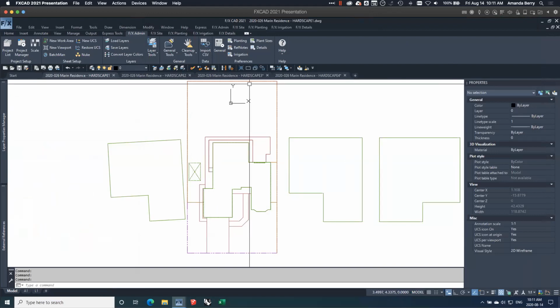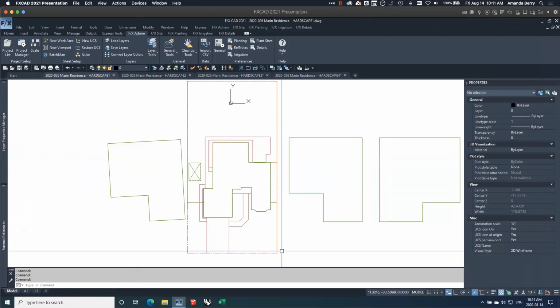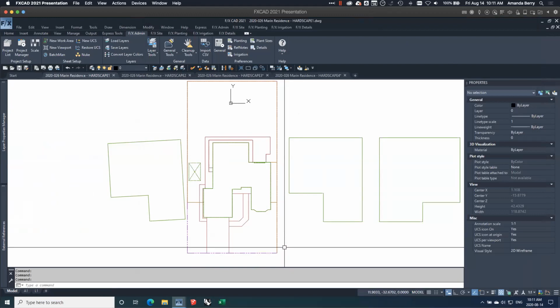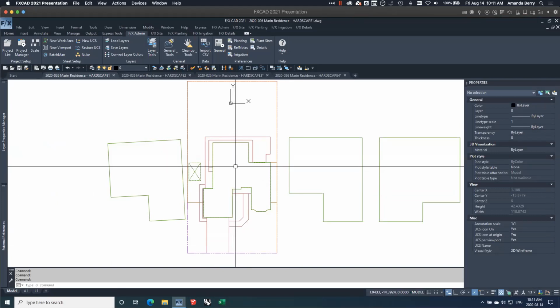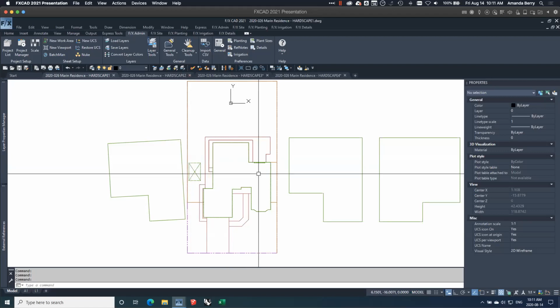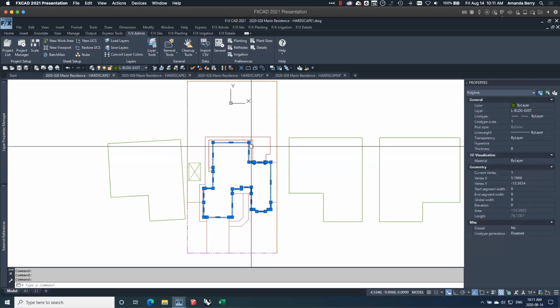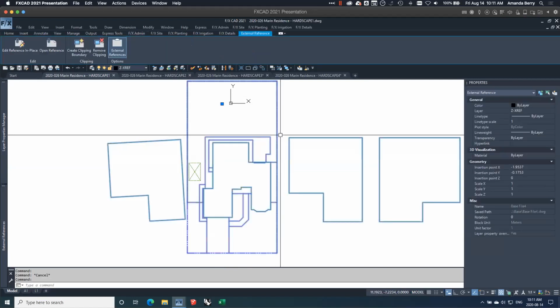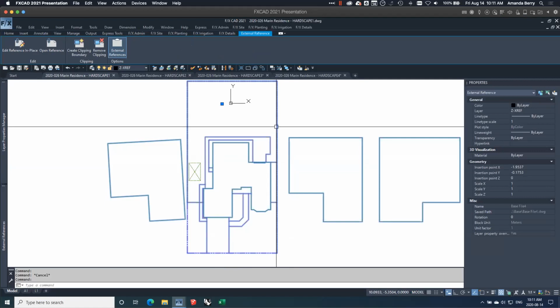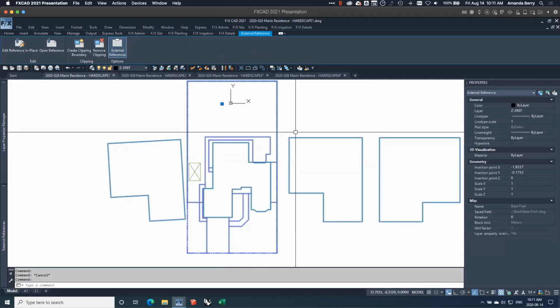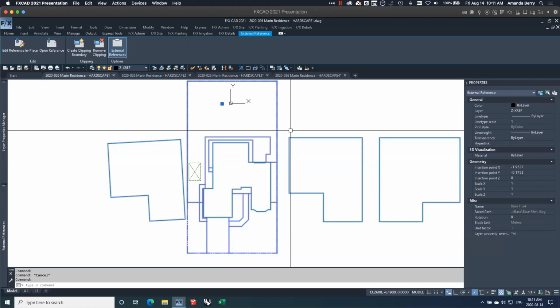Really, to get to where I've gotten to at this point, all I've done is taken an aerial photograph of, hey, this is my house, and traced over it, along with refined it with some site measurements with just polylines, and I saved all of that into an XREF because I always keep my base information inside a separate drawing from where I'm going to be doing any of my hardscape or planting or irrigation or anything.